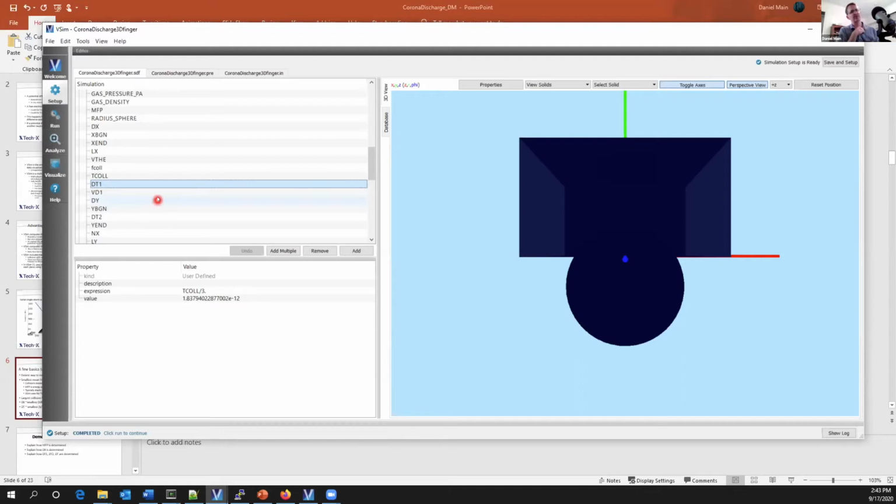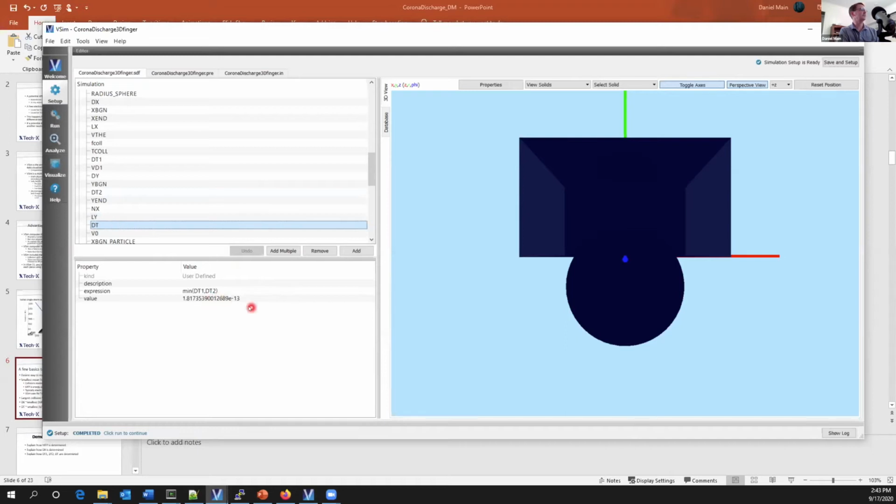But there's actually another constraint on the time step, and that is that as my electrons accelerate due to the potential difference, they pick up speed, and an electron can't cross more than 1 cell in a time step. So I also compute that time based on the potential difference. And then for my final one, I just take the minimum of those. Again, none of these are numerical instabilities, but rather you will just get incorrect results.